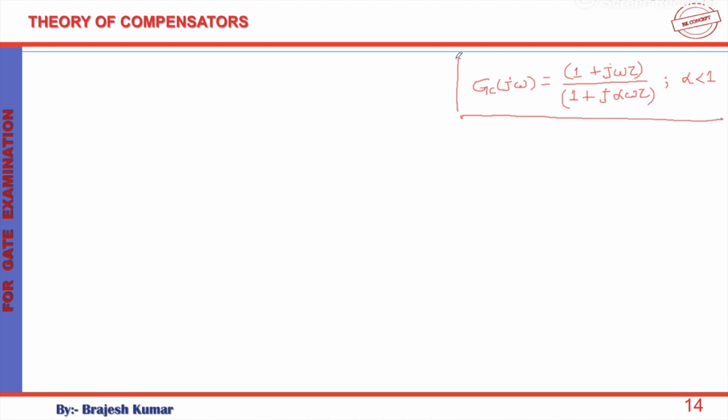So now if you try to draw a Bode diagram for this, how will you approach it? First we draw the amplitude plot and then we draw the phase plot. Why do we want to draw the amplitude and phase plots? So that we can analyze how this system behaves with respect to the change in frequency. The first step in the case of a Bode diagram is to find the corner frequency.